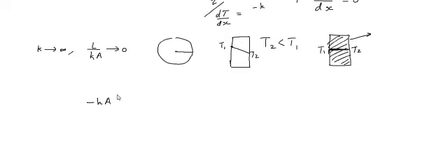So the heat convection equation is given by hAs times T minus T infinity, where As is the surface area, T is the temperature at any particular time small t, and T infinity is the ambient temperature. This will be equal to rho Vc dT over dt. That is the rate form. Rho V c is actually mc, mass times specific heat, so this is mc delta T with respect to time, or per unit time. So we can write it as rho Vc dT by dt.